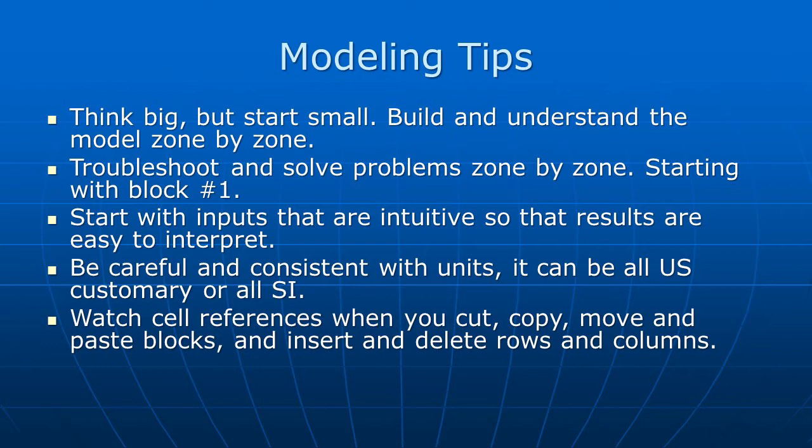Be careful and consistent with units. You find that units sometimes are in U.S. customary units in some specs, and SI units in machine set points, and so you've got to either go all one way or the other, or make sure that your formulas account for the differences and that you understand what they're doing. And then if you do named references and things like that, and you're cutting, copying, and pasting blocks around in the model, or inserting and deleting rows, make sure your references don't get lost and that they're in fact pointing to where you think they should.